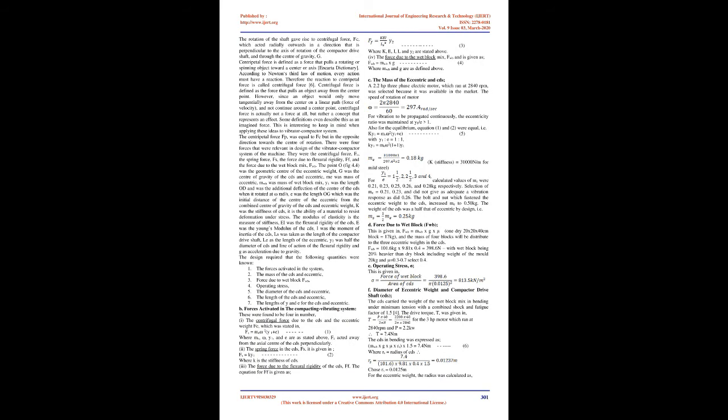A. Theoretical analysis of the compacting, vibrating system. The principle of the concrete vibrator compactor block making machine is the eccentric weight. The eccentric weight, based on calculation for size, was fastened on the compactor drive shaft, CDS. The CDS was also based on design as carried out below. The attachment of the eccentric to the CDS caused an out-of-balance rotation that sets the long face of the mold to vibrate, a process which compacted the wet block mix.